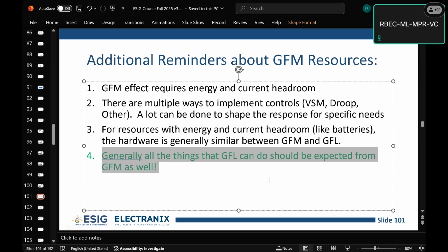And the StatCom vendors would be on it. They would make it fast, 50 milliseconds. And then all through their controls, they would have special controls to keep it stable at 50 milliseconds. They would have adaptive gains that would keep their gains approximately right to give you that response time for any system strength. And did we really need 50 milliseconds? No, most of the time not. But those carried forward into grid forming specs.